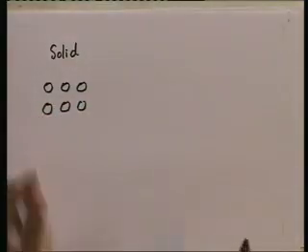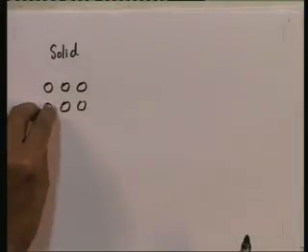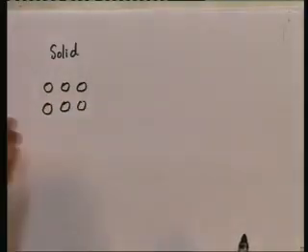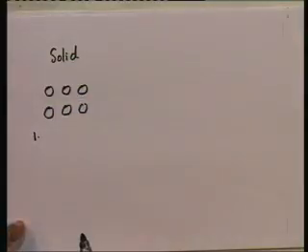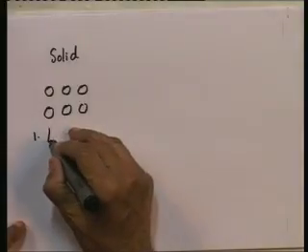So, the transfer of energy by conduction is because of the lattice vibrations, and these vibrations are more in the higher temperature region than in the lower temperature region. So, in a solid, one mechanism by which the transfer of energy takes place is lattice vibrations.